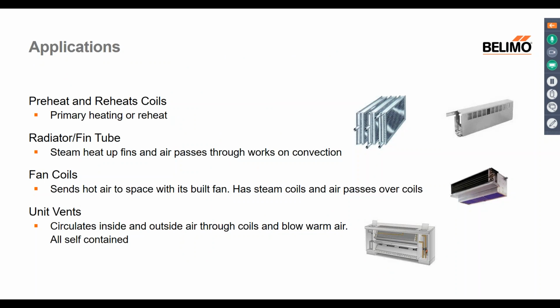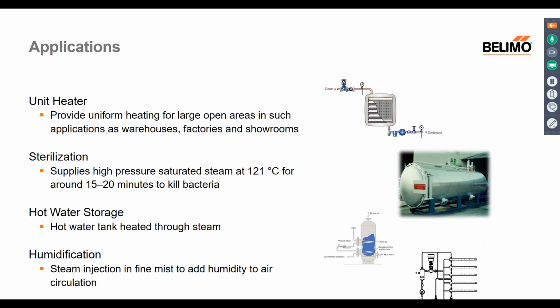So applications, where do we use steam coils? Preheat and reheat coils in our air handler units, radiator fin tube. In the Northeast, I still have a lot of radiator fin tube that is steam driven. Steam fan coil units, unit ventilators, very common in schools that they still use low pressure steam. Unit heaters, of course. Sterilization, not too much in our industry, but we do see quite a bit of it. Hot water storage. Humidification, I do see quite a bit.